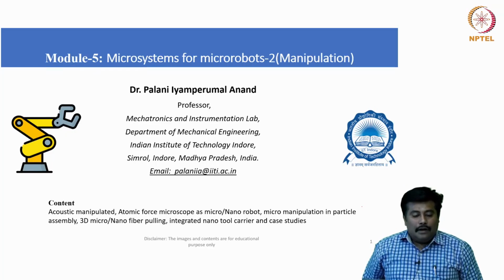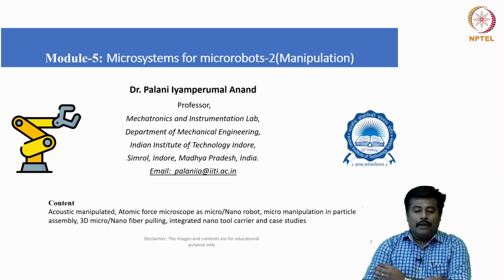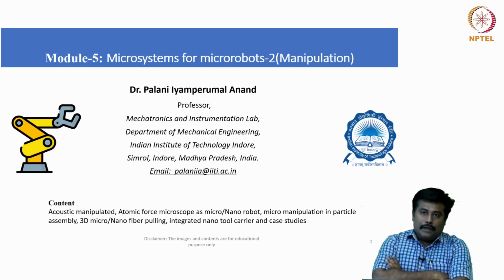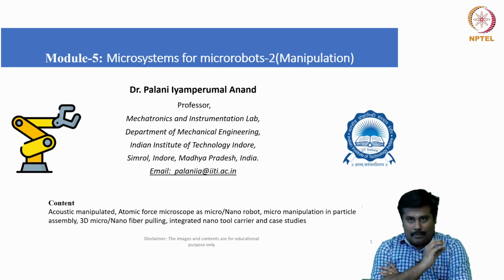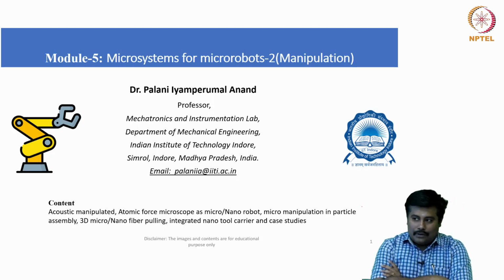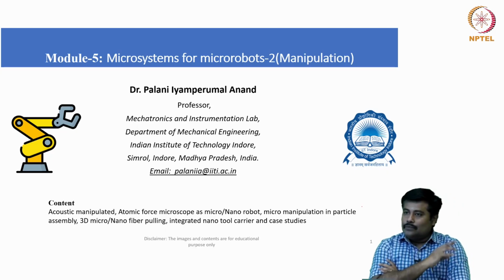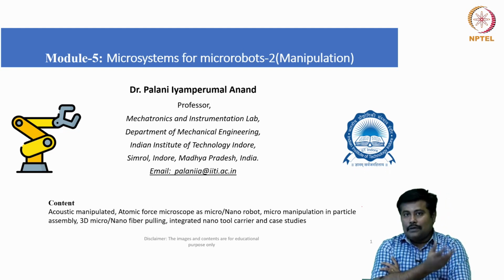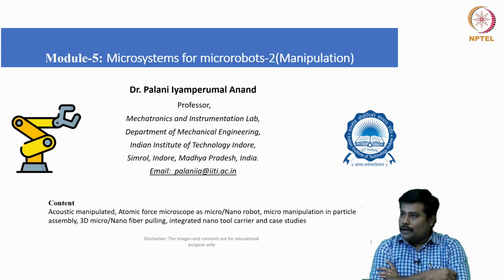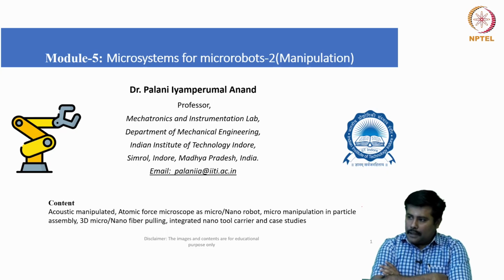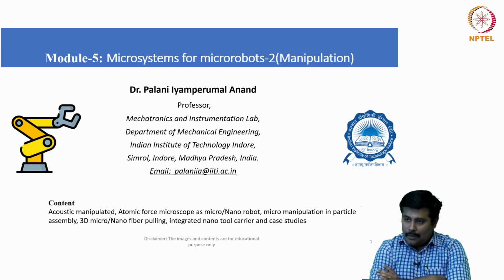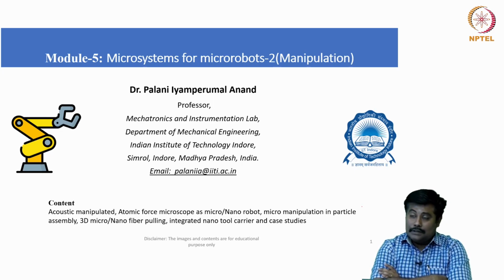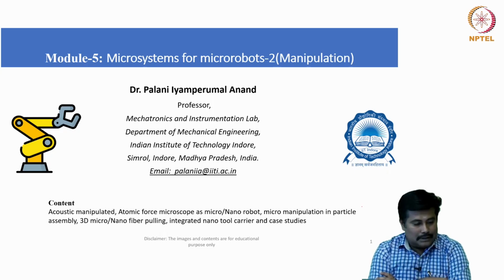Today we will discuss microsystems for micro robots, basically focusing upon manipulation-related applications or manipulation-related mechanisms. In the last module we discussed mostly micro engines and micro pumps, the different configurations of micro pumps. In the case of micro engines, we discussed piezo-based systems, thermal-based systems, then fluid-based systems. We also had some discussion about magnetic helical-based systems, etc.